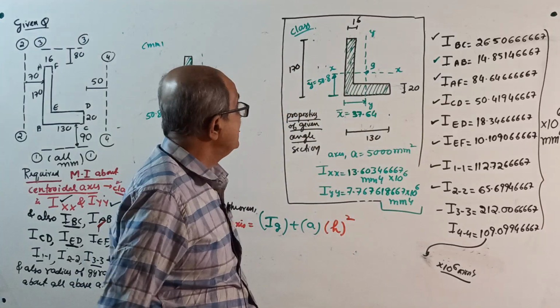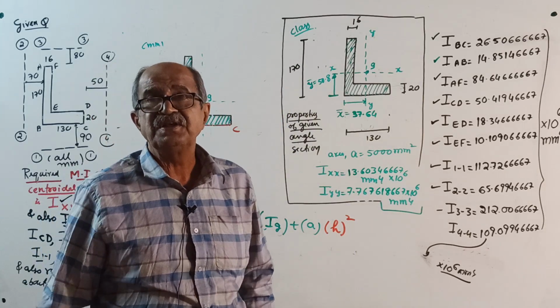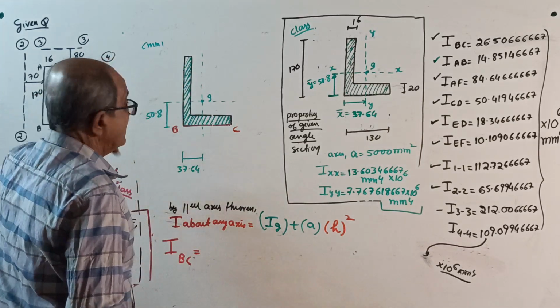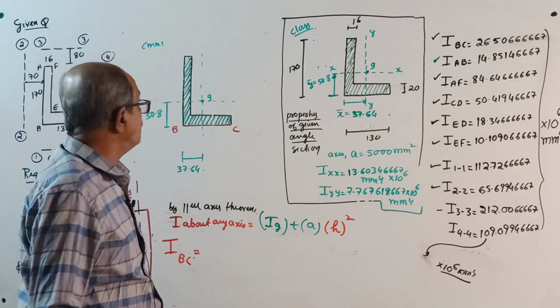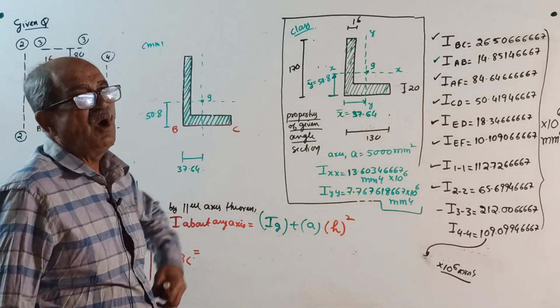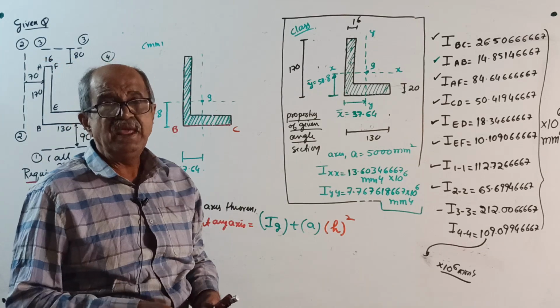I will dictate something. What I am covering now is very important for steel structures. Because see, you write here, the given section is an angle section. Of course, one side is 170, one is 130. That you will not get in steel structures. In steel structures, you will have unequal angle and equal angle.